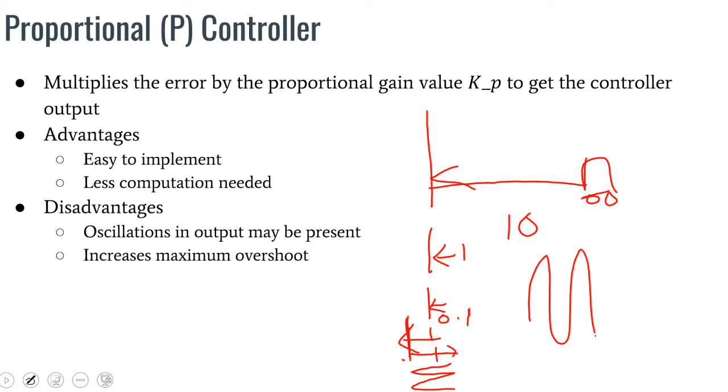That is the oscillation of error that we would find in proportional control. It will go back and forth around the targeted value. That is what we would encounter with proportional control, and we want to avoid that using other approaches.